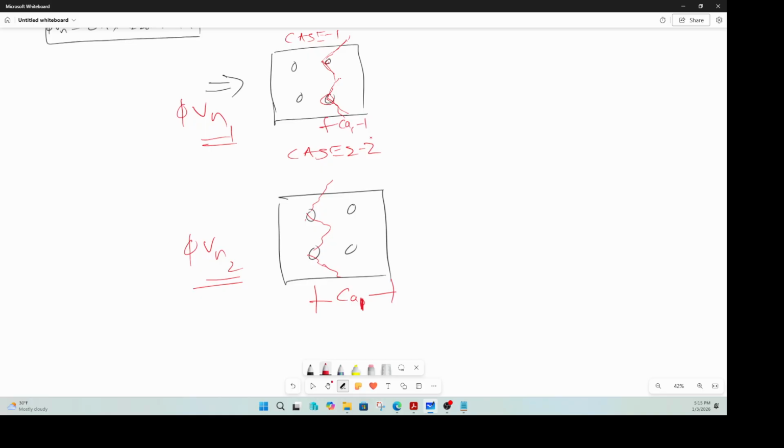And the same thing, when you look at it from this view, you have your pedestal, right? 24, this is 24. You have your two anchor bolts, but that distance where the crack will form is 1.5 times the bigger ca1. That means this distance is huge. That's how the failure looks, right?